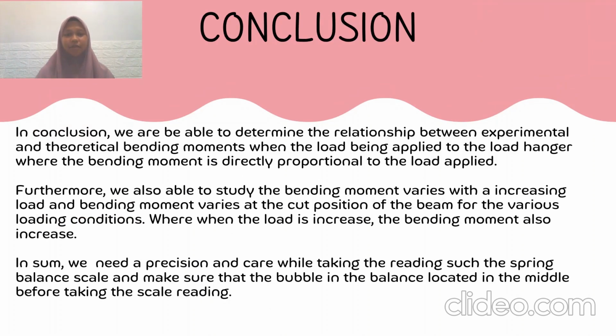Okay, the last slide, which is the conclusion for this experiment. In conclusion, we are able to determine the relationship between experimental and theoretical bending moments when the load is applied to the load hanger, where the bending moment is directly proportional to the load applied. Furthermore, we are also able to study how bending moment varies with increasing load, and how bending moment varies at the cut position of the beam for the various loading conditions. When the load is increased, the bending moment also increases.